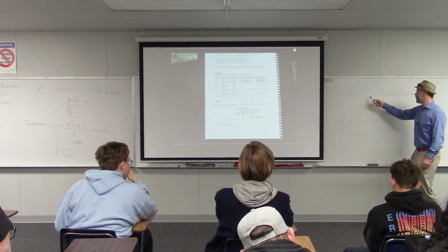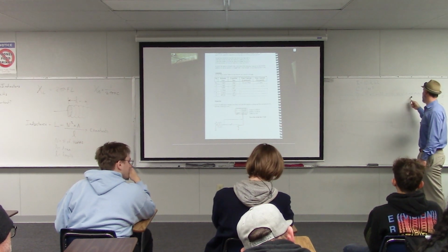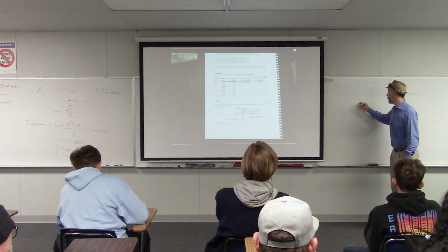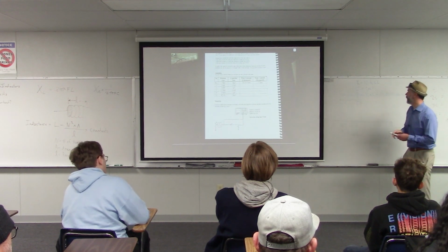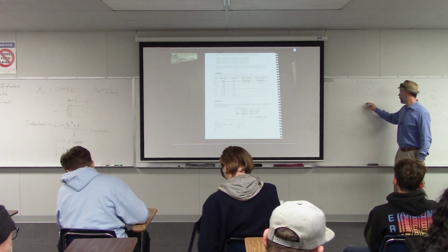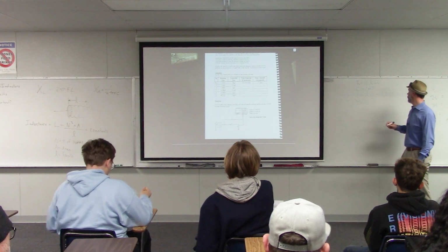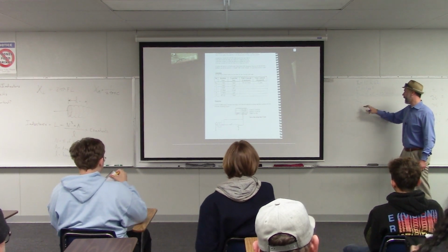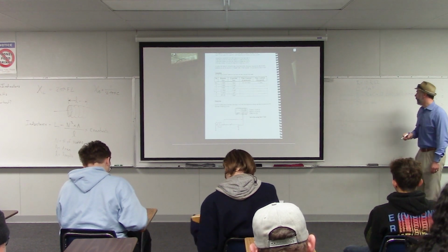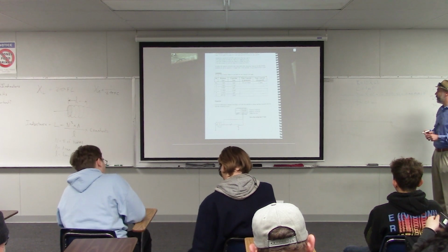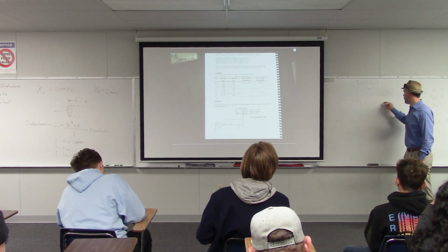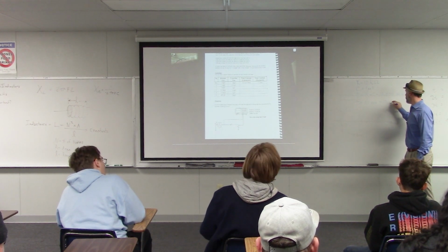So in this case, tau should be 10,000 times 0.000001. So does anybody have a calculator? What does that come out to be? 0.01, okay, maybe. 0.01. So the unit of tau is time, so that's seconds. So that would be 0.01 seconds. So that would be 10 milliseconds.